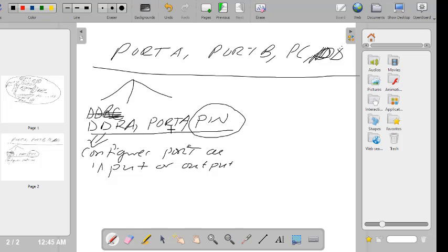This is also the port register itself, which is associated with port A. And then we also have the pin A register. This is also a register that is associated with port A itself. So this is very confusing. Yes, we're saying port A. So what's the big deal? Pin A, of course, DDR, but the port A, similar word to that one. But I want to mention that these three are the registers that are associated with every port.